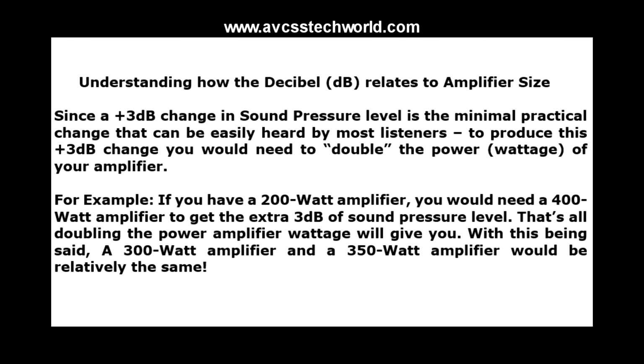Understanding how the decibel relates to amplifier size. A +3 dB change in sound pressure level is the minimal practical change that can be easily heard by most listeners. To produce this +3 dB change, you would need to double the wattage of your amplifier.